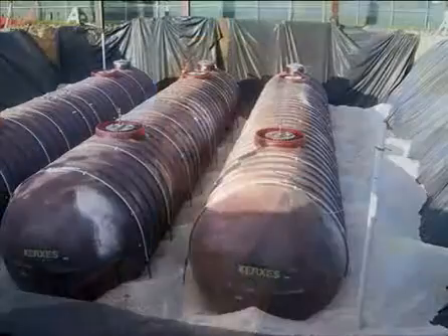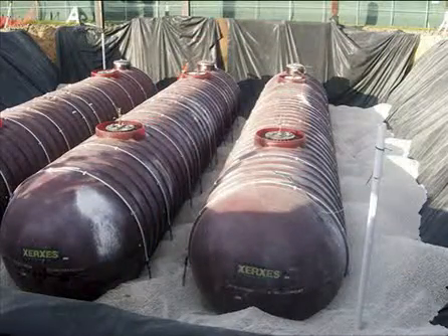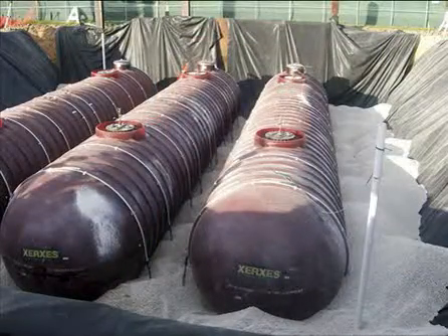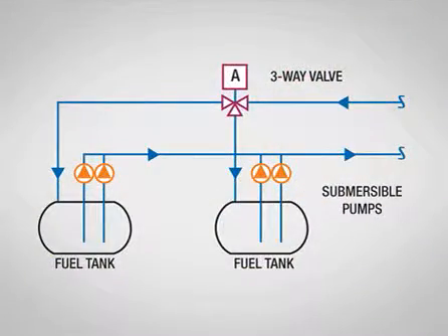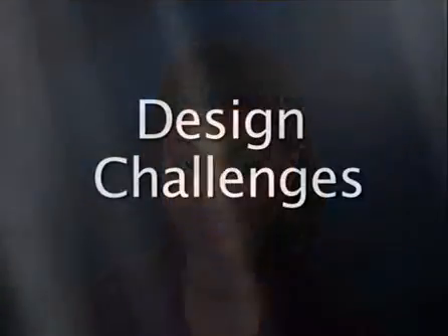Most mission-critical systems require at least 2 tanks so that a primary and redundant source are provided. Since the tanks are monitored closely by environmental rules, there is always the risk that a tank will need to be removed from service because of a real or perceived leak monitoring issue. In some cases, potential fuel quality issues may dictate the use of multiple tanks.